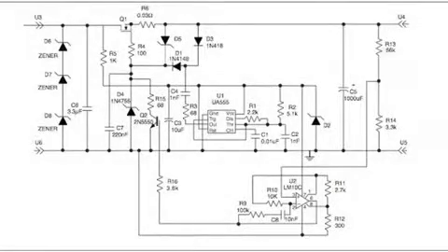Usually, this is achieved using an input shunt transorb to clamp the spike to a reasonable level, followed by an active clamp circuit. This diagram shows a typical clamp that uses FETs to reduce the voltage at the output to the minimum level the DC device can tolerate. In this circuit, Q1 is the main clamping element and must be sized to handle the power dissipation needed.